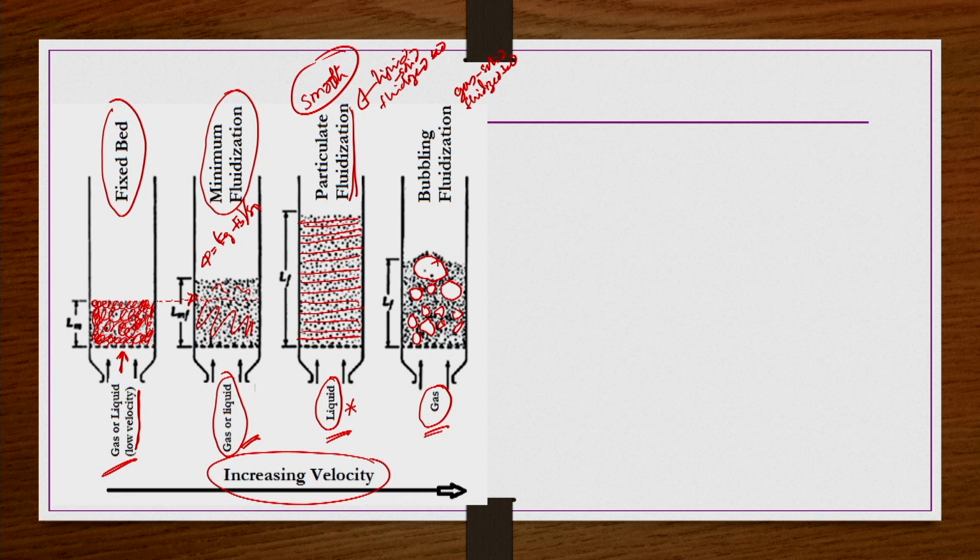That is the reason this behavior, if you find such fluidization in a gas-solid fluidized bed, is known as bubbling fluidization. In some books you also find the terminology aggregative fluidization, because earlier it was believed that these particles were agglomerating and forming clusters, leaving more space for the gas to form voids or bubbles. But subsequently no reasons were found that particles form aggregates. So, bubbling fluidization is the more appropriate terminology here. Okay.